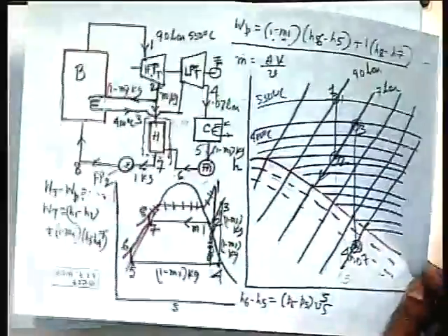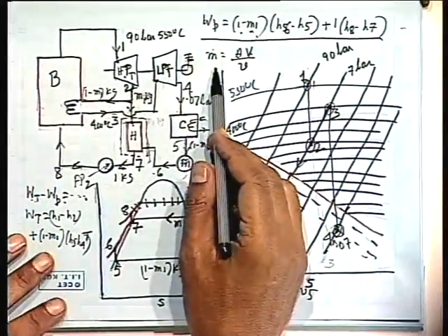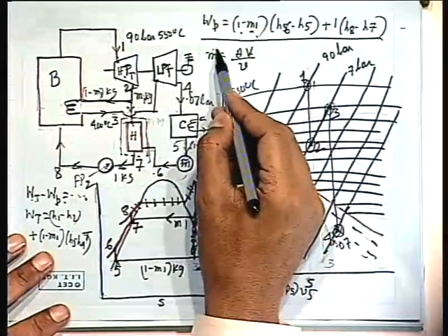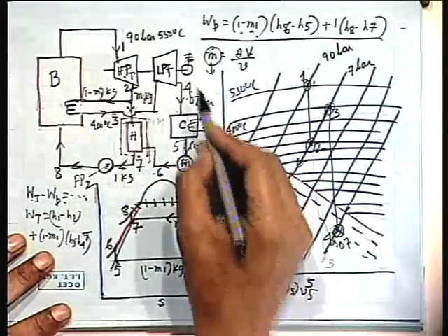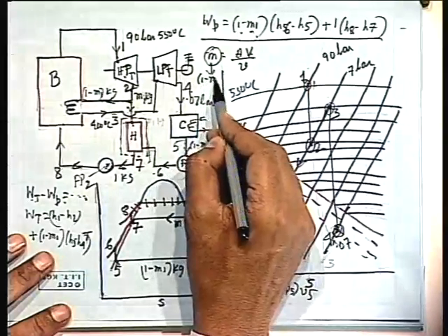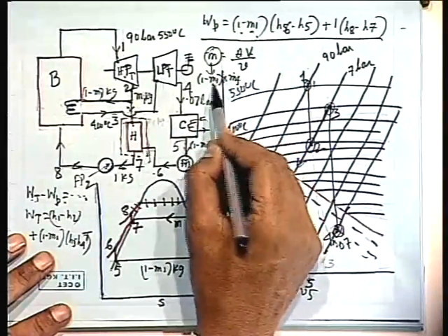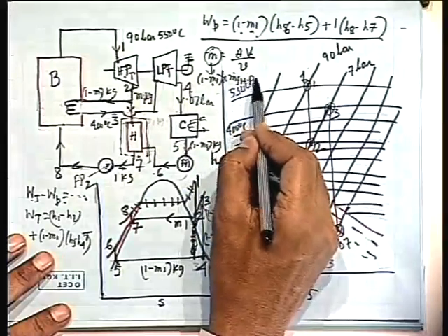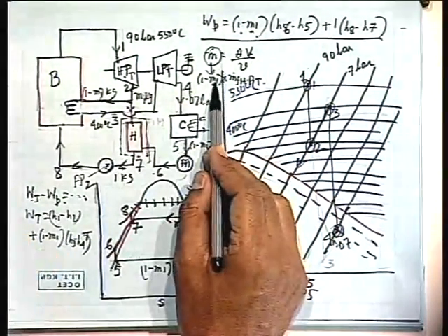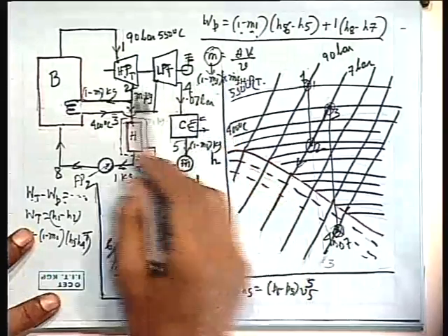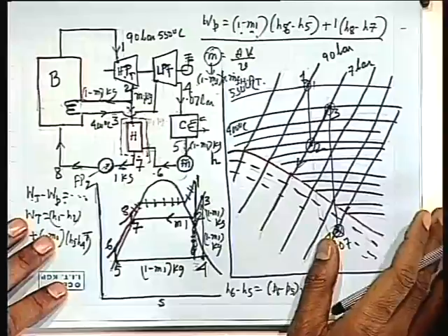Okay, yeah. But in that case, the value of the M dot should be the M1 dot, sir. The value of the M dot, oh, I have not, yes. The value of the M dot is 1 minus M1, into the mass flow rate of this thing. That means this is per unit mass flow rate. Mass flow rate to the HP turbine. I am sorry. M1 is the fraction per unit mass. So 1 minus M1 into the mass flow rate of the HP turbine. Everything is known. That is the actual mass flow rate. Very correct. I am sorry.